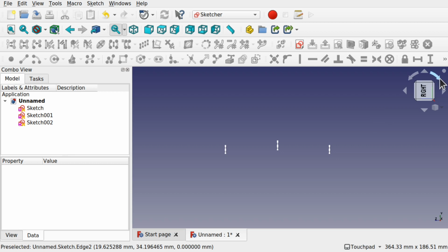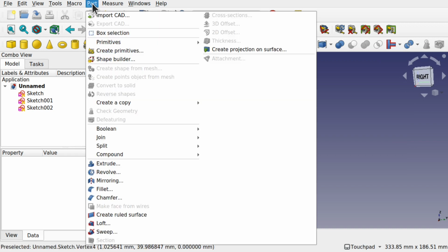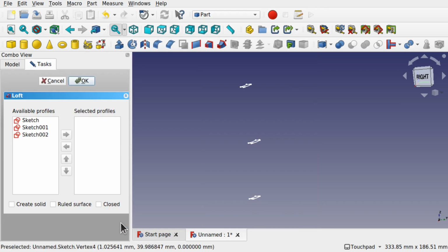So this is now ready for lofting. Remember, we've got an angle I think that allows for 12 rotations of these. So this is going to be one panel. So let's loft through this, coming over to the part workbench. And we're going to use the Loft Tool, this one here, or at part and Loft. I always show the drop downs because the icons on the toolbar can be placed anywhere and it will differ depending on how you arrange those toolbars.